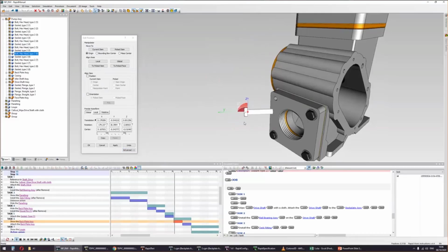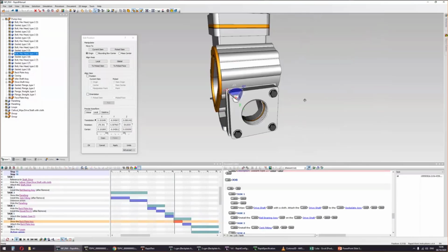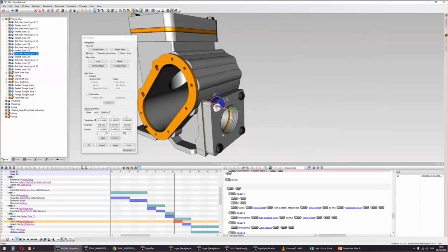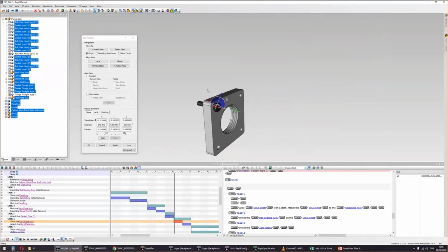To do that, we simply grab this reference point, hold the Shift button on our keyboard, and move two parts together, like so. As you can see, this bolt now perfectly fits together. If I switch off everything else, this, of course, works in the opposite direction as well.